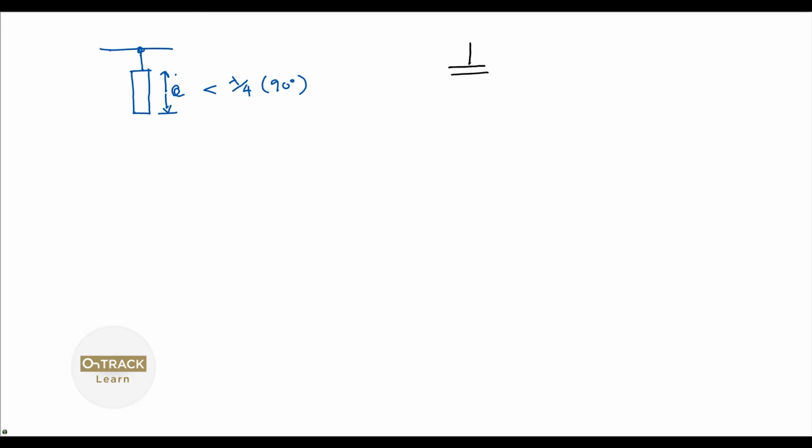So if you have a shunt capacitor, and why is this shunting? Well, because remember, this is a transmission line segment on a PCB. There's always ground plane underneath it. If you break up your ground plane, or if you have a void underneath where it's just dielectric but no ground plane, then it won't behave this way at all. It'll have a different impedance and it'll have capacitance out to other objects. It won't be a proper formal transmission line segment. But because there's ground plane under it, that is capacitive, right? So this appears like a shunt capacitance.